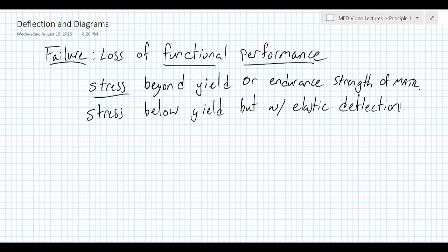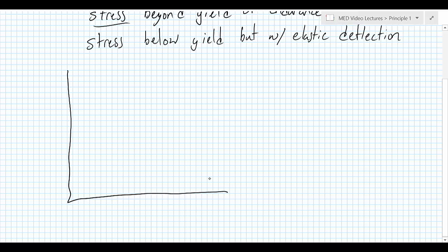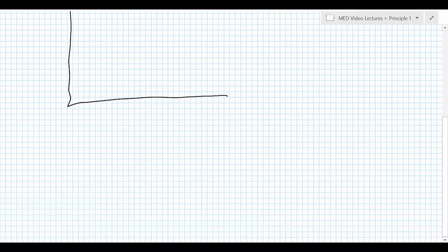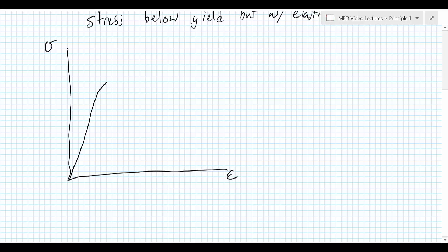So recall a diagram called the stress-strain curve. And every material has its own stress-strain curve. When we put some normal stress, like in the Instron machine test, on this part, it experiences some amount of strain. Steel and aluminum tend to have this straight part, up to a point where it starts to behave slightly differently and then eventually breaks.